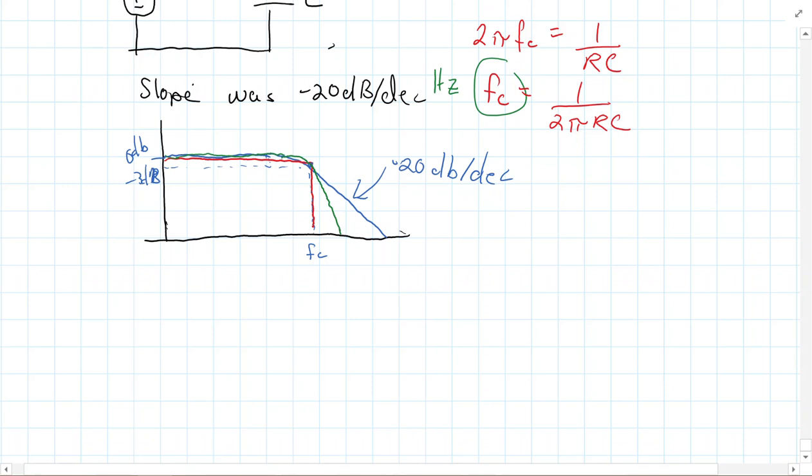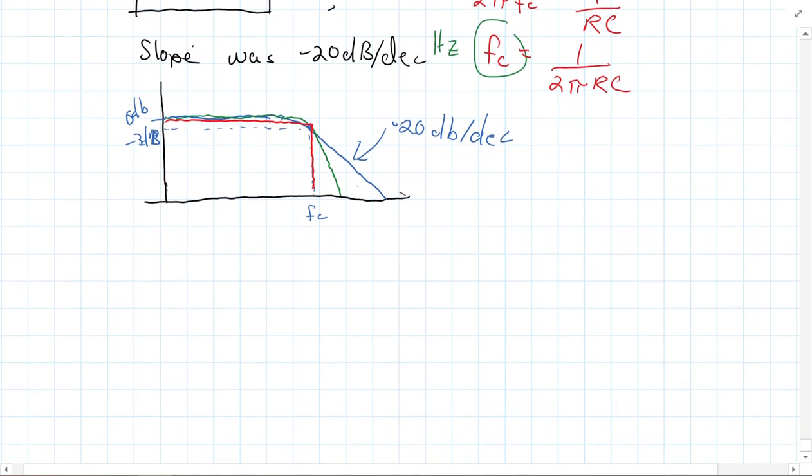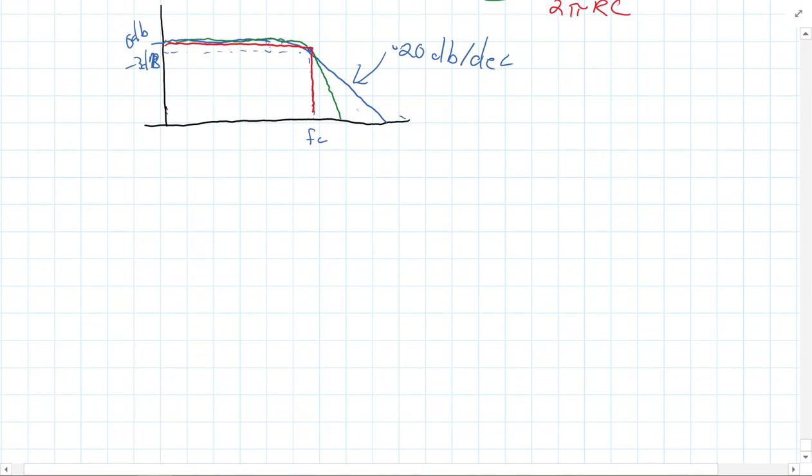But we can see here the difference is the green one, we're cutting off the low frequencies much better, in the sense that there's still some frequencies that have some power getting through on this first order, and we still have some frequencies getting through on the green curve, but they're much lower ones, or closer to the cutoff frequency, what I should say.